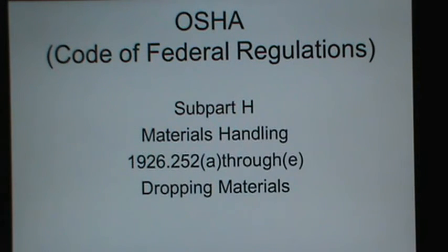All right. Next paragraph, when debris is dropped through holes in a floor without the use of chutes, the area onto which the material is dropped shall be completely enclosed with barricades not less than 42 inches high. The next paragraph says all scrap lumber and so forth shall be removed from the immediate work area as the work progresses.